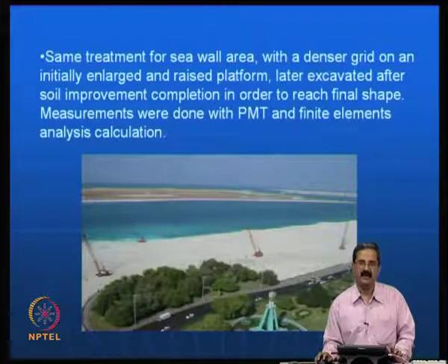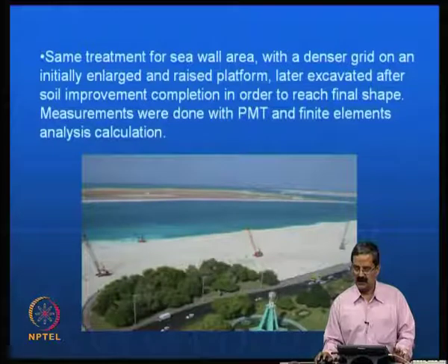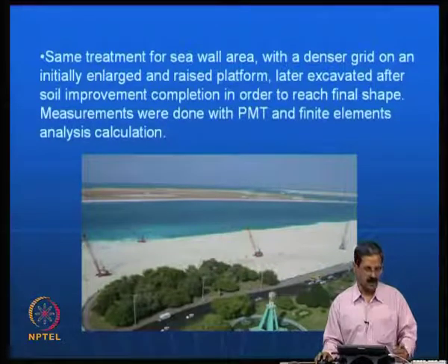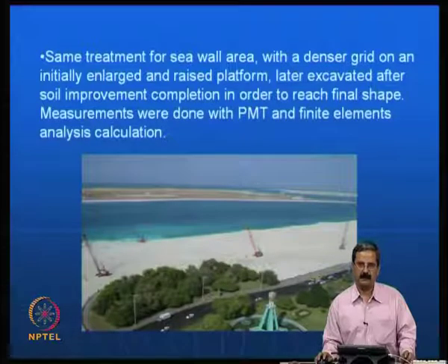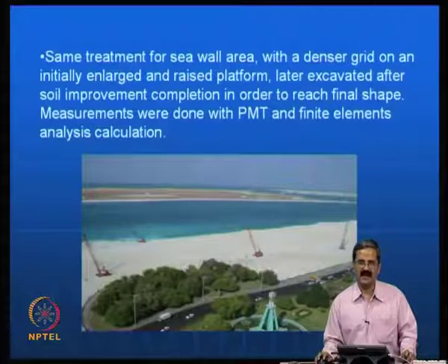There have been many case studies even in India, particularly in many of the coastal areas, where dynamic compaction was done. It was done in fly ash ponds. It has been quite effective because the method itself is quite simple: it only involves a weight being dropped, and everything is pre-designed, for example the height and the spacing.